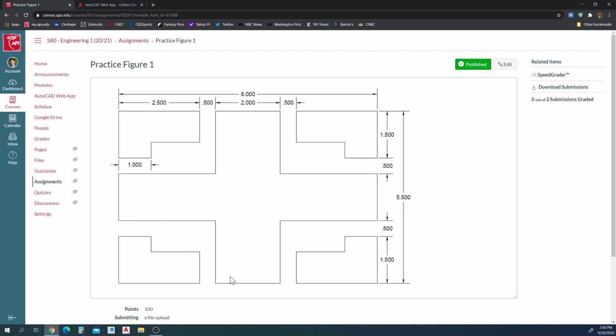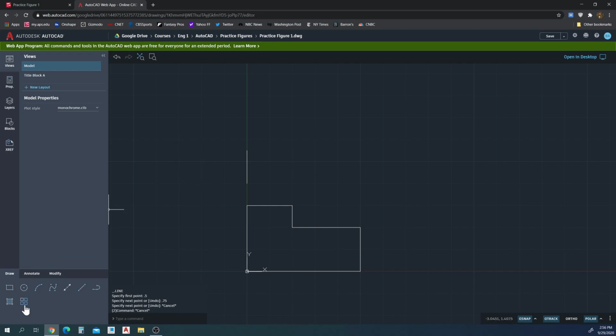And 2 inches. So this line is 2 inches. Same idea. Line command, snap to there, and then pan to snap to the points. Pan there. You get that trailing green line. So it's an extension. How far away do you want to be from there? We want to be 0.5 inches away. Okay, there we go, 0.5 inches away. And then we want to be a 1 inch line because it's half of the 2. Perfect. And then we're just kind of connecting these two lines together.